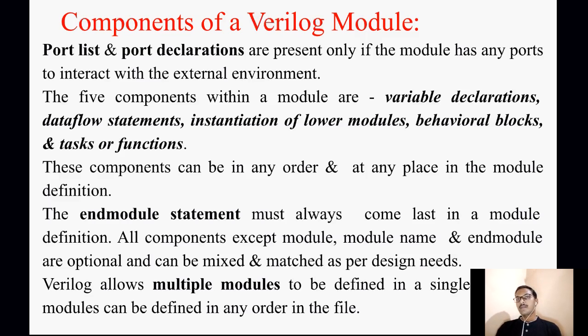So these components can be in any order and at any particular place in the module definition. And the endmodule statement must always come last in the module definition. All the components except module, module name, and endmodule are optional and can be mixed and matched as per the design requirements. Verilog allows multiple modules to be defined in a single file, and the modules can be defined in any order in that particular file.